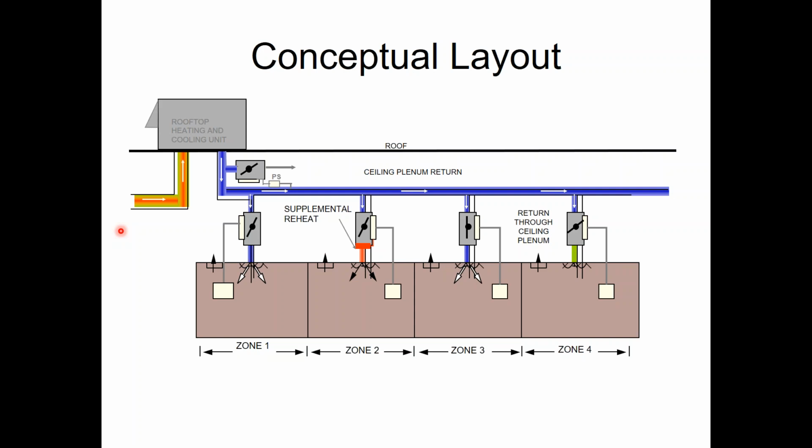Hardik says, suppose all the rooms are in cooling mode, then the supply temperature from the RTU will be based on the minimum temperature required from each room. All right, so on the VVT system, we don't look at the supply temperature at all. It's just going to be whatever happens, happens. So specifically, the way the supply temperature is going to work.